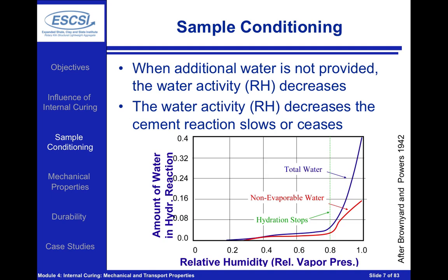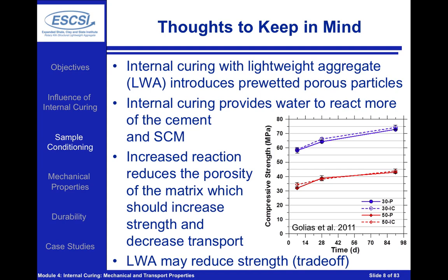So at this point, really what we're saying is nothing that we haven't already learned in sort of good concreting practices. By keeping water inside of our concrete, we're going to react more of the cement, and by reacting more of the cement, we're going to improve the overall performance of our concrete. So some thoughts that we really want to keep in mind here as we start to move forward.